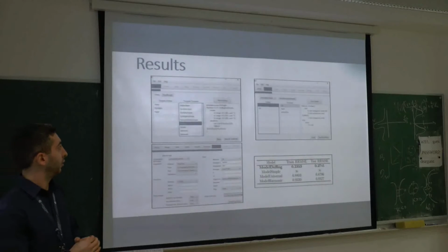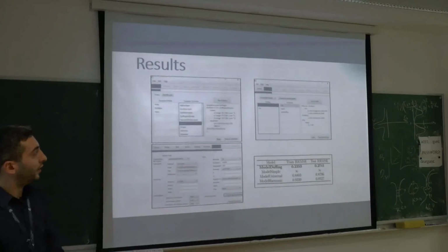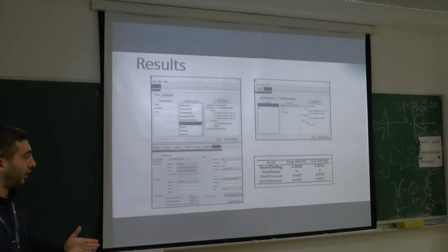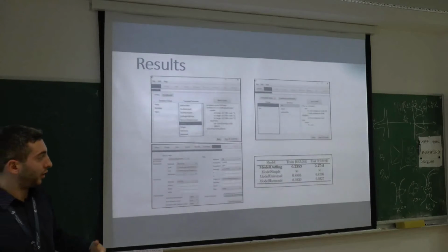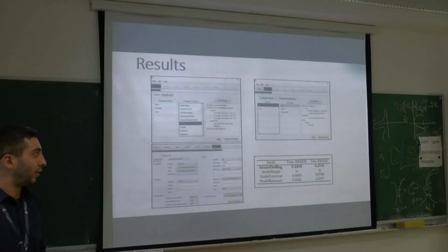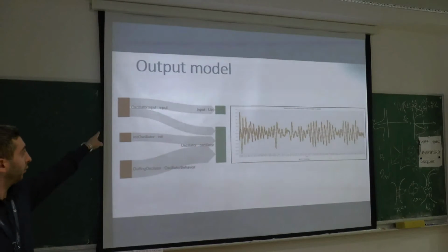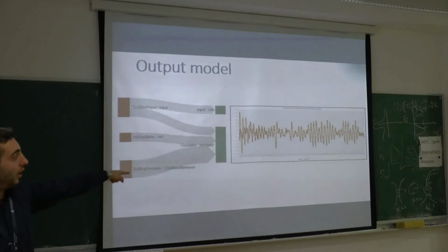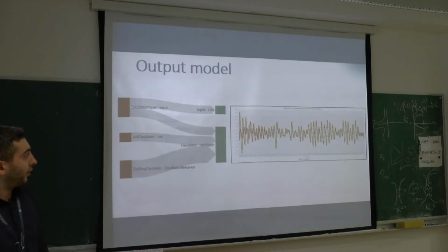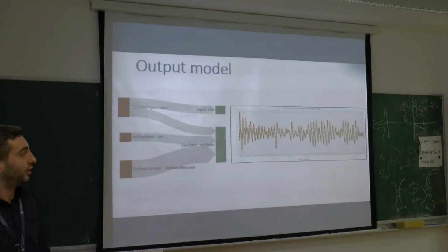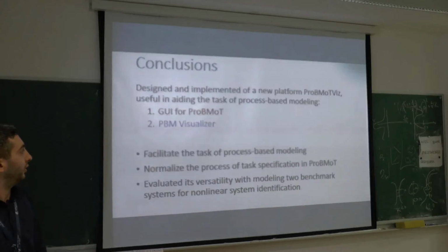This is how it looks in the GUI. We can see the encoded different behaviors, and in our particular system we say that we have an oscillator with unknown behavior. So it results in 4 models, out of which the best results are obtained with the Duffing oscillator, which in fact is our system at hand. This is how it looks. We can see that we have input voltage to the oscillator, it's initialized, and it has some Duffing oscillator behavior. This is the plot between the measured and simulated value of the output displacement of the oscillator.